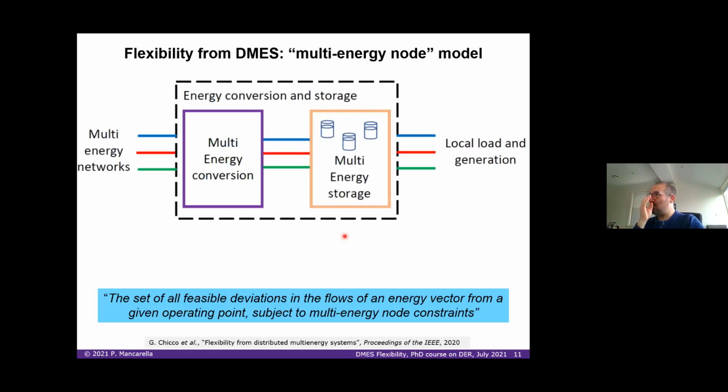And in the same way as we introduced the power node before, what we discuss here is the so-called multi-energy node, because now all the equations that we wrote before in terms of one energy vector, electricity, actually power, we were only modeling active power in the original power node model formulation, here becomes completely multi-energy, in the sense that we can write the same equations in vector, in matrix form, where now you have multiple energy networks, vectors, and sectors as an input and as an output.